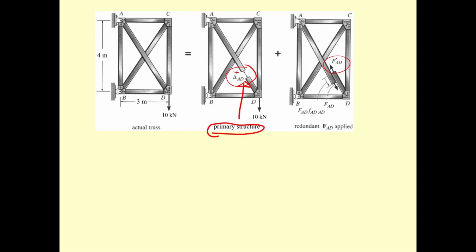If you say AD is in tension, tension is going to be positive, right? So the force here is going to change to this one, and the force here is going to change to this one. The forces at the points are going to be in these directions, following Newton's third law.